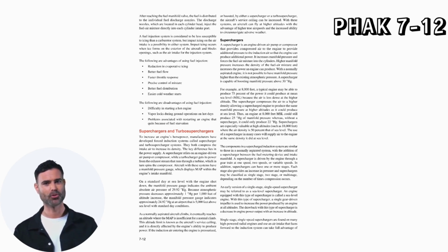Superchargers and turbo superchargers. To increase an engine's horsepower, manufacturers have developed forced induction systems called supercharger and turbo supercharger systems. They both compress the intake air to increase its density. The key difference lies in the power supply. A supercharger relies on an engine-driven air pump or compressor, while a turbocharger gets its power from the exhaust stream that runs through a turbine, which in turn spins the compressor.